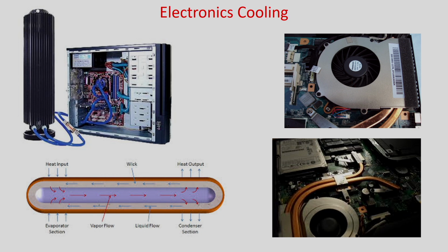So, there is no external force, and the advantage is that you can bend it. So, here you can see you can bend it and put it towards the outside, and the evaporator section you can put on the chip, and that way naturally this heat is removed from the chip to the ambient. So, this is one example of convective heat transfer. Nowadays these chips are also cooled using some fluid, and this fluid is passed through this tube, and for more heat transfer or effective heat transfer, these fluids are used to remove the heat from the chip.